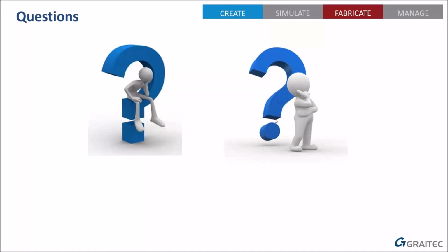So I would say it's a bug. You're not doing anything wrong. Unfortunately, at the moment, that's just the way it misbehaves slightly. When you do joint copy, it does do the stair width incorrectly. Change the value back to 1000, change it back to the right value again, and if necessary, move it sideways. So I hope that answers that question for you.